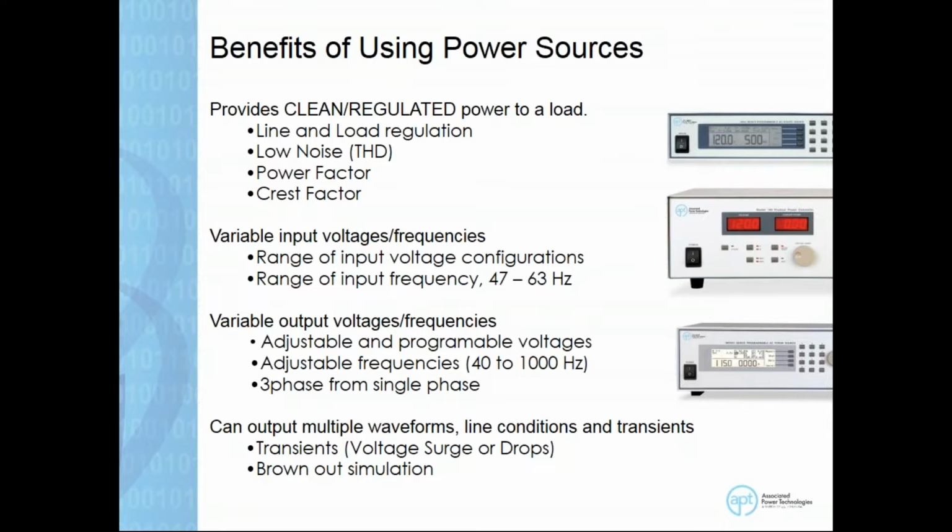Crest factor is also something that's measured. Crest factor is the peak value of a sine wave divided by the RMS. So if you have a really peaky sine wave, the crest factor is going to be really high. So you want to make sure that you can measure the crest factor, and that the source can even provide the power at those crest factors.